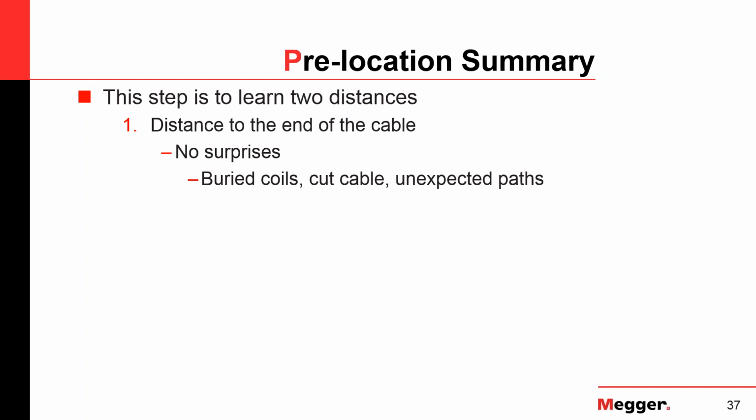So if you're not sure if you have the actual end of the cable, you can always verify by physically making that connection, so you actually find the end of the cable. Because this is very important. To find the end of the cable is one of your main priorities when you want to attack these problems, because as we had in this example before, the cable is 1,000 feet long and the TDR flags it at 550 open end. What is going on there? So a way to verify is, if possible, short the two at the end together, the conductor and the concentric neutral, and see if the TDR trace changes. That already tells you a lot.